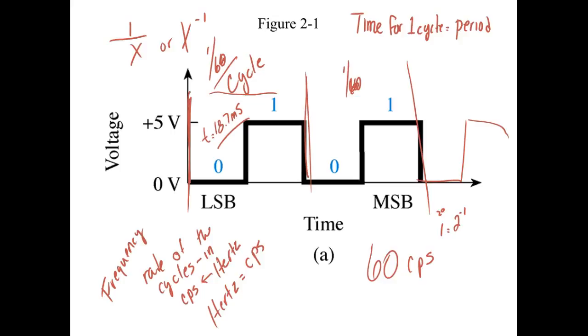So if I know the period, how can I find the frequency? Take the reciprocal of that, right? So F is equal to 1/T, and of course T is equal to 1/F. They're inverses of each other. So if I've got an oscilloscope that measures time, I can calculate the frequency by taking the time for the period and then taking the reciprocal. Digital scopes can give you the period because they're computers, and it's nothing but math anyway. That's all this information it's giving me on my scope screen up here. I need to turn that off.